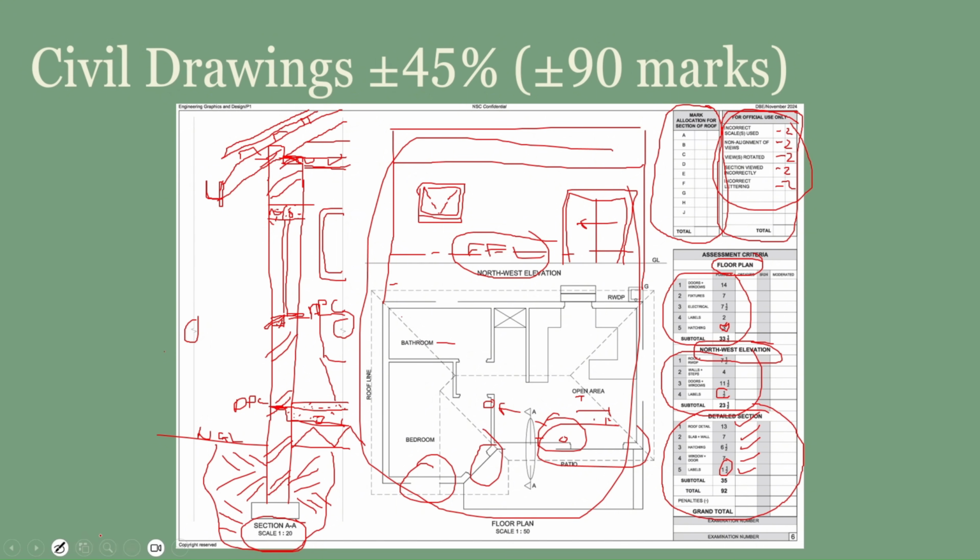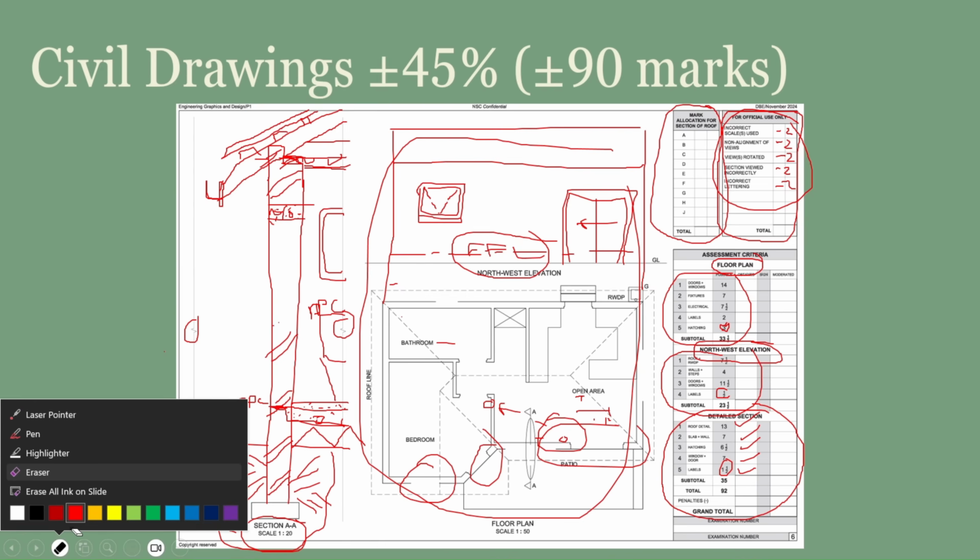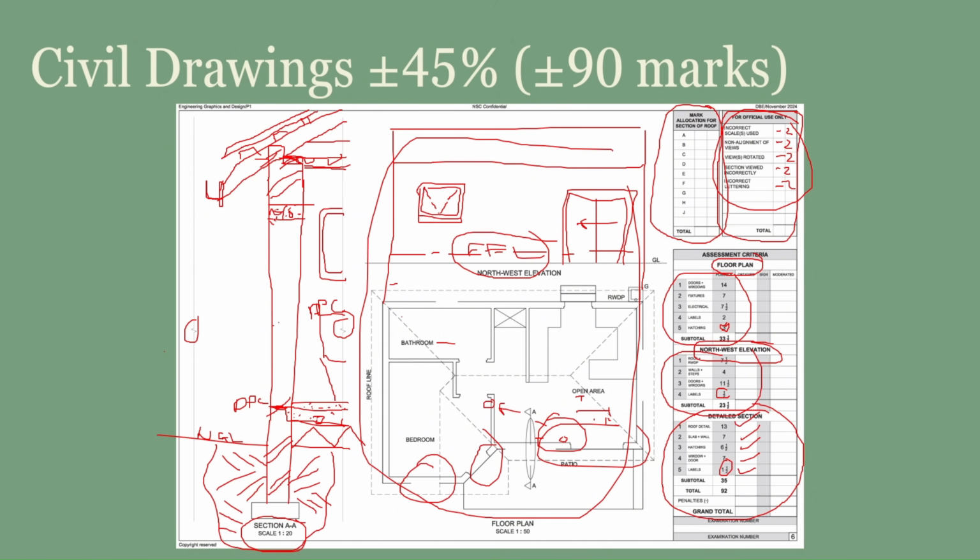Now, let's say you needed to draw in a door. There's going to be a lintel. And for the door, we're just going to see the frame of the door, which will look something like that. And then we will take all those corners down to the finished floor level. You can also add here finished floor level for another label. And that is that for question 4.